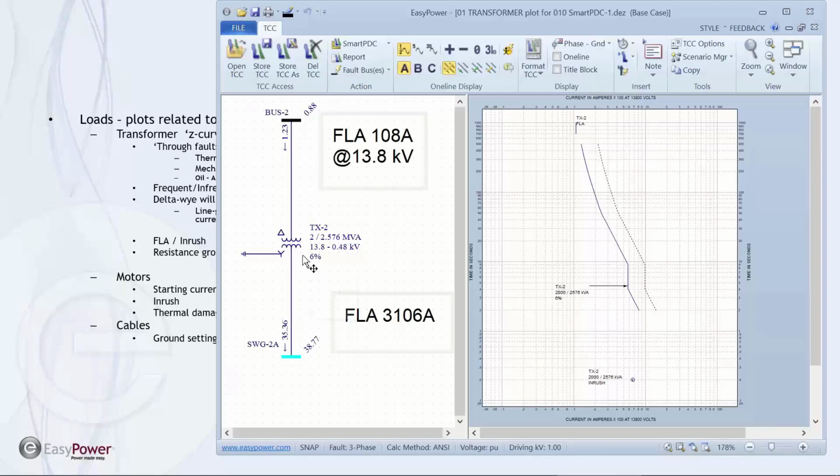And what the full load current tells us is that these are the maximum currents that will occur in that particular bus, in that particular range for that voltage. So this is normally the full load current for a full load on the secondary side. If you look down here at the bottom band where the cursor is, it reflects the coordinates under my pointer.